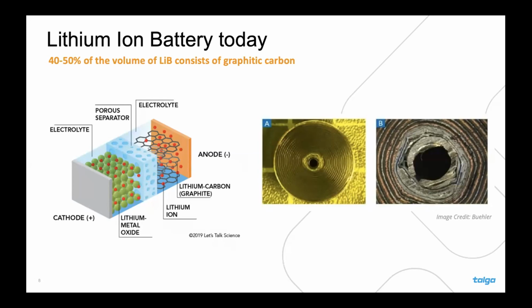Graphite requirements for effective lithium-ion battery use are low surface area, size that is typically in excess of maybe 15 microns, that's lateral size, and ultra high purity. There's no direct replacement for the graphite in the anode with a graphene product. It doesn't, however, mean that graphene has no use in this space.